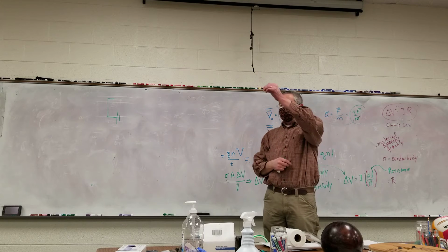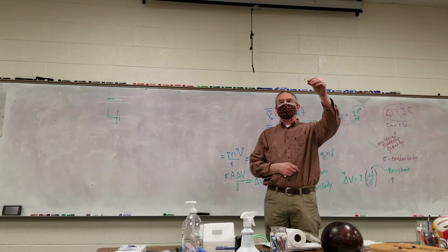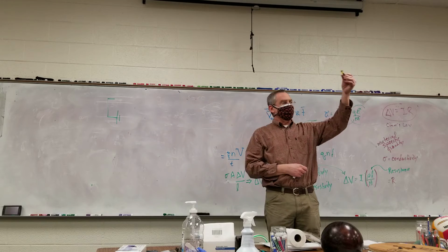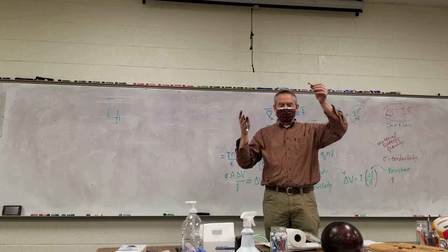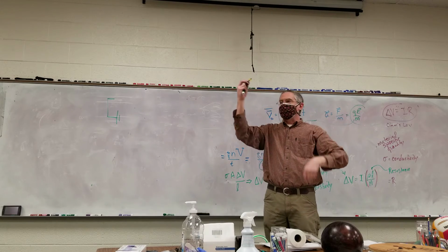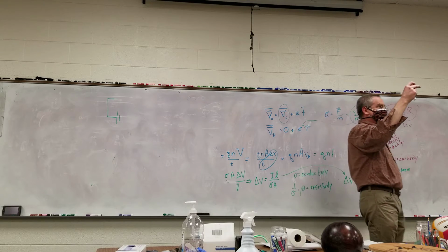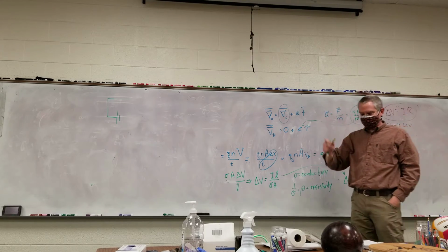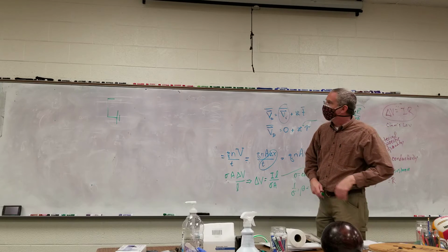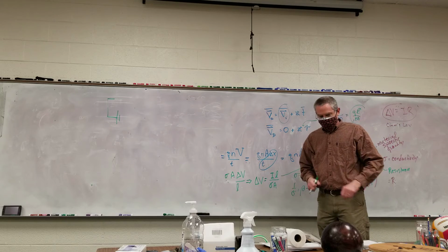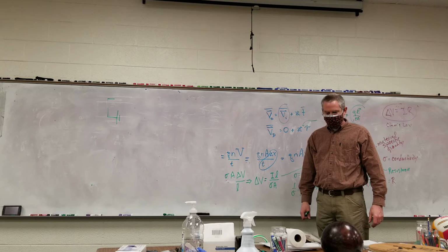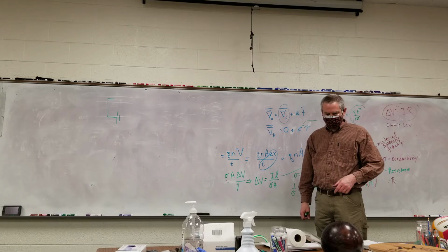So this is what's called a 4-band resistor. The first three tell you what the resistance is. The silver band tells you the tolerance, and this is, I believe, 10%. So it tells you what the resistance is, plus or minus 10%. And I think almost all of ours are silver band.